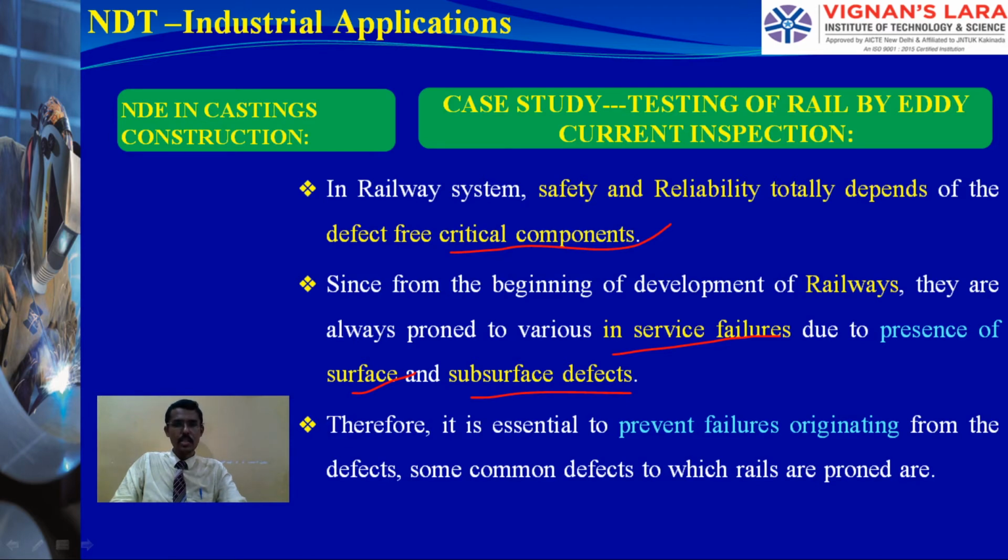Rail tracks repeatedly crack, the wheel friction causes wear concentrations, and a crack may form due to heat. So these are the common defects. We have to check for those common defects and try to eliminate them.